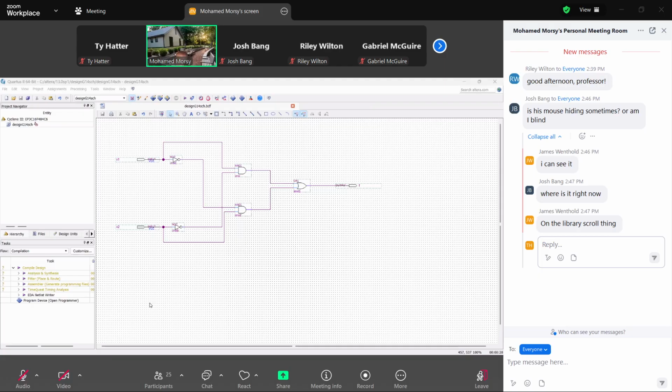Now we'll do the same thing. What we do, who remembers what is the next step? Edit, run the simulation? Did we edit, change the times, the length of the simulation? Yeah. So we click on edit, insert node or bus.